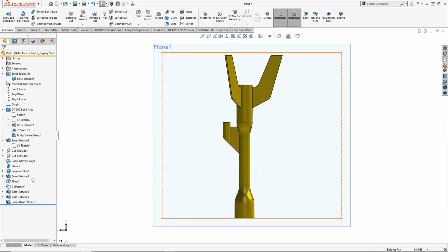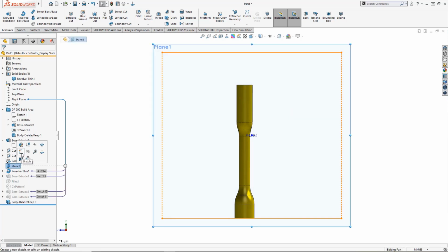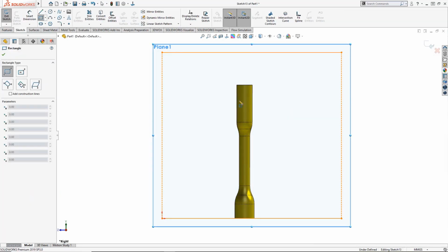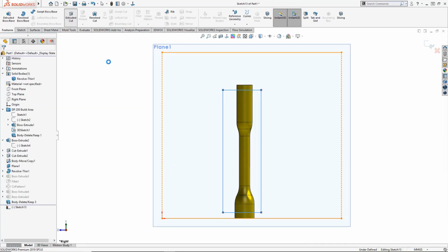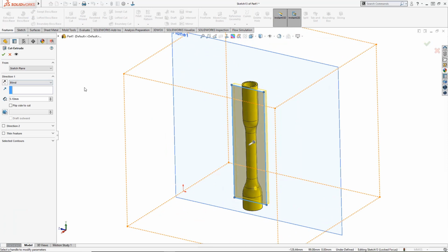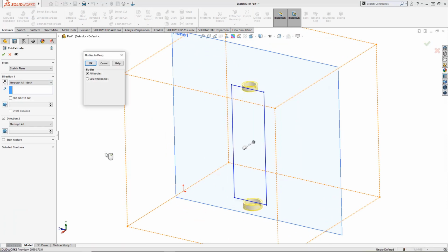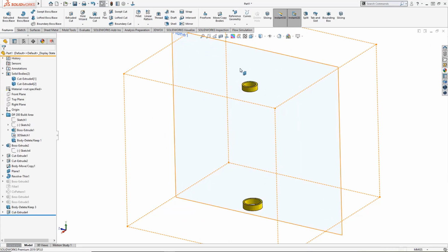Now when I have some critical fit issues, for this one I'm going to go ahead and actually just get rid of some of those finishing features, and I want to hack this model in half. I'm actually going to go ahead and hog this thing right out, because what I want to test really quickly is whether my motor is going to fit in that top diameter and whether my bottle is going to fit in the bottom diameter. Because what you'll find with 3D printing is that tolerances might be somewhat tricky to keep.